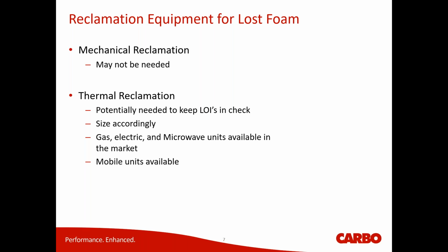Reclamation equipment for lost foam. Typically, mechanical reclamation is not needed. The only time it's needed is if you're using some kind of a resin in the material itself. There's a couple of foundries I've been in where they're making such large, intricate castings that they're actually using a little bit of phenolic urethane or furan in there to help bind the material up around the styrofoam as well as just packing it in. In those cases, you may need to use a mechanical reclamation to help break up the chunks.